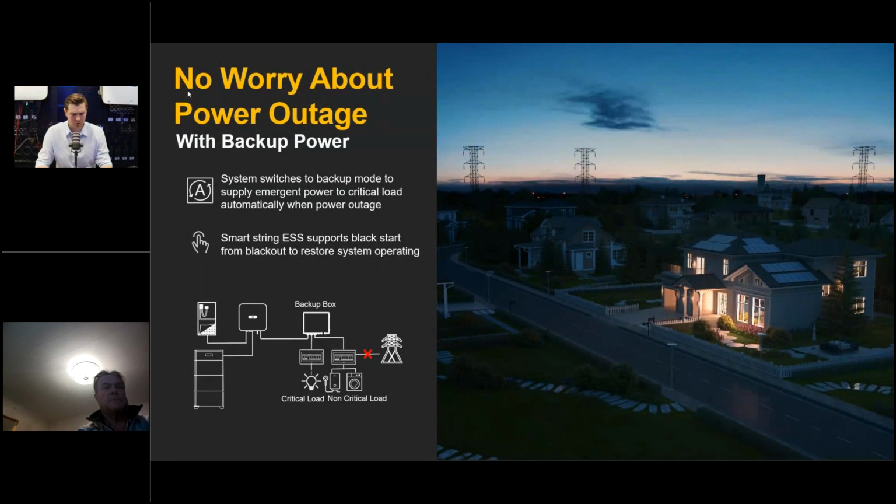The backup box is the accessory I told you about a little bit before. It allows us to supply our backup phase when we have a blackout. From the battery, the energy is transformed by the inverter and provided to our loads. Unfortunately there is a huge limitation: if we have the three-phase backup box, it can supply only one backup phase.